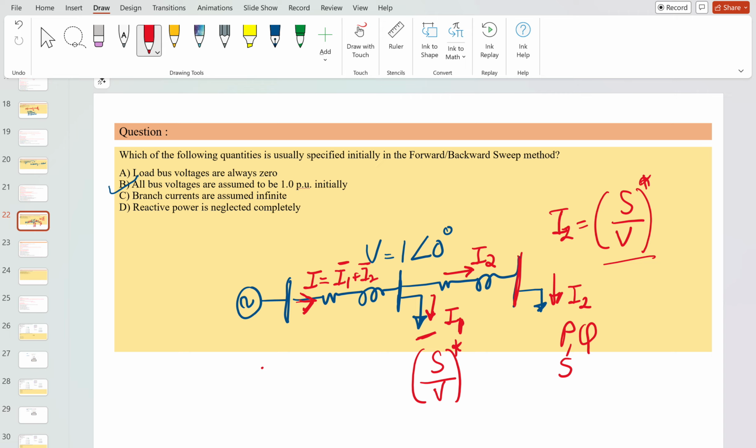After that you will find the voltage here. When the current flows, the voltage will dip, since power is required by the demand. An important point to remember: in a transmission network, P is mostly coupled with the frequency and Q is mostly coupled with the voltage.